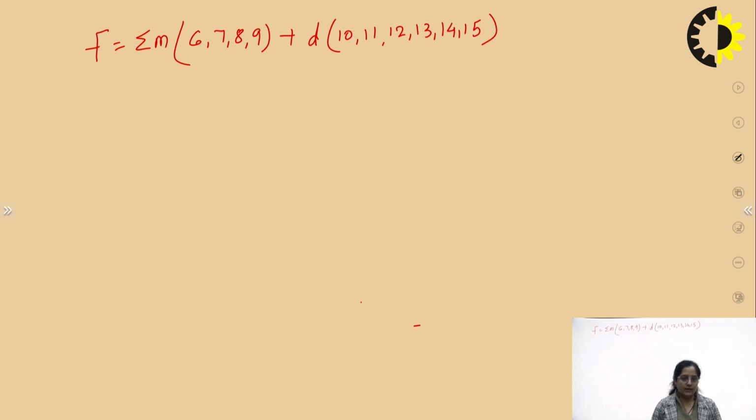But to solve the expression and find the minimized expression, we have to consider don't care also, like when we are pairing in the Karnaugh map, we consider don't care in the pair of 1s. Similarly here also we have to consider don't care as a min term and solve the expression. So we start with column 1.